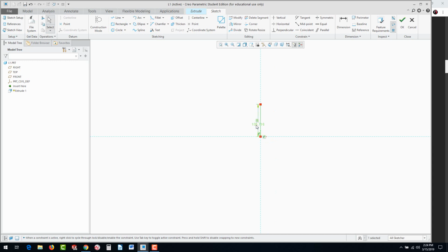The reason I like to do this is because it's going to set our scale, and so that part is 3 inches in height. And then we could actually hit right up here to the refit. There actually is an option in the Tools Options, I believe, that will automatically fit it to the screen as you model it. I'm not going to go there right now, though. Go ahead and go to the line tool. If someone knows where it is, please share that in the comments below.